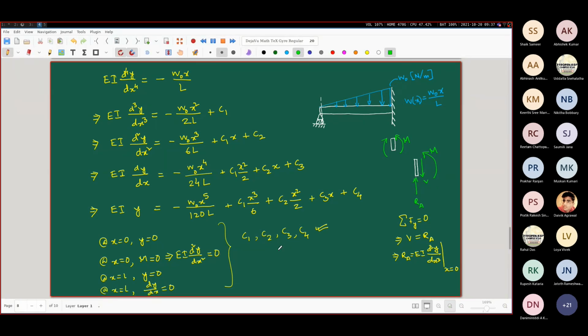So this is the general idea regarding statically indeterminate cases. Here, the way that the problem was set up, we had only one extra unknown compared to the number of equations available to us, statically speaking, meaning that we had 4 total reaction unknowns, whereas we have 3 equations of static equilibrium.